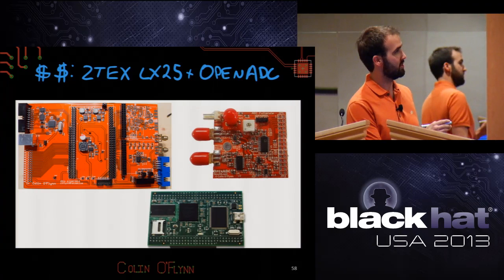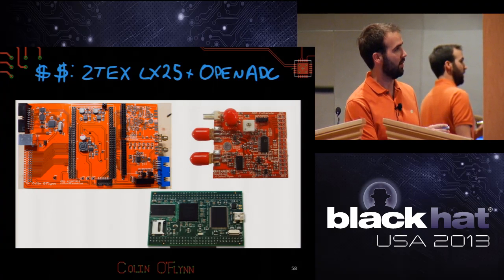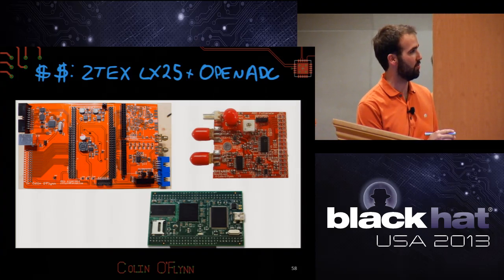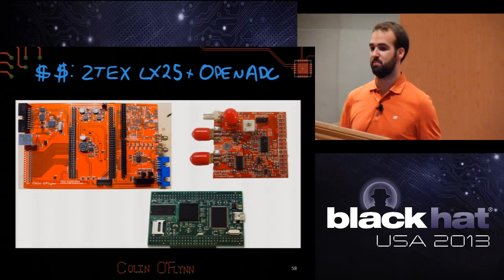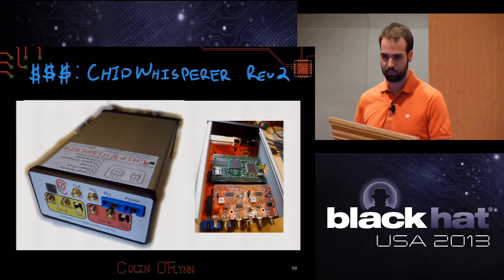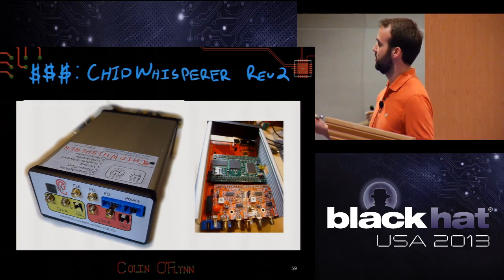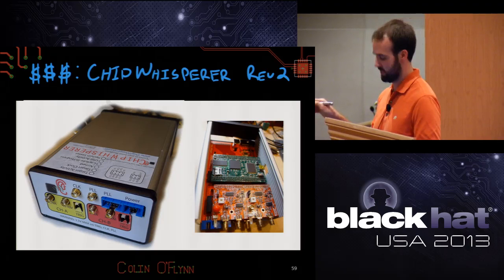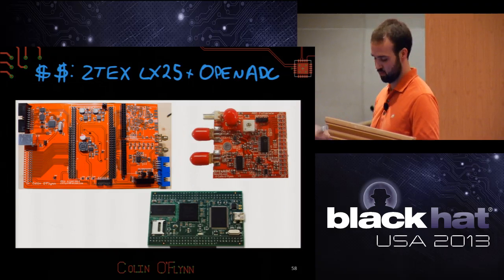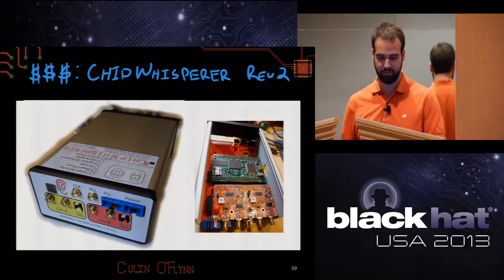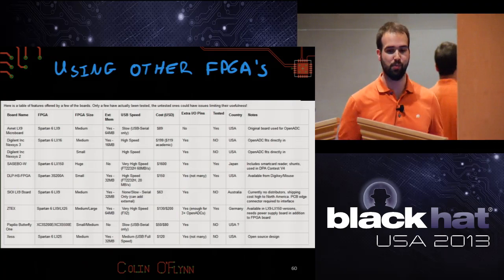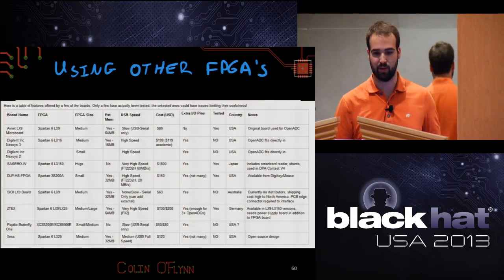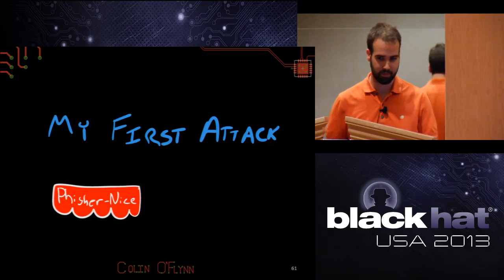So there's these boards, all the designs are here. And you can use this with an FPGA and either mount this ADC board or build an ADC board on it. When you combine everything, you get a complete system for doing this side channel analysis. And eventually I'm trying to build and sell them as a complete package, but this is the exact same thing as this. It's just one's pre-built, one requires you to do a bunch of soldering. Or, if you do FPGA development already, you may have a suitable board. Typically any Spartan 6 board, because that's what I'm using, can easily be modified.